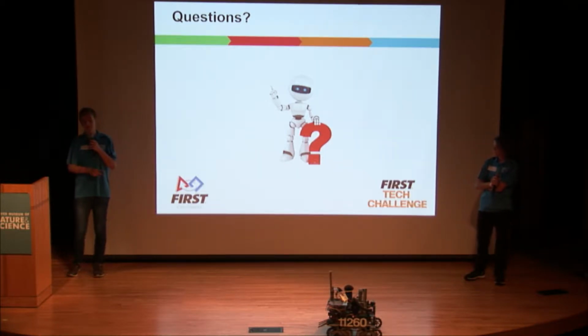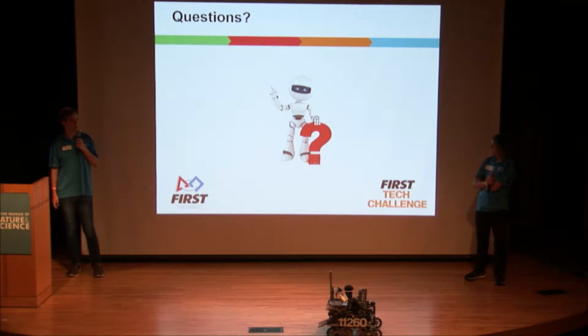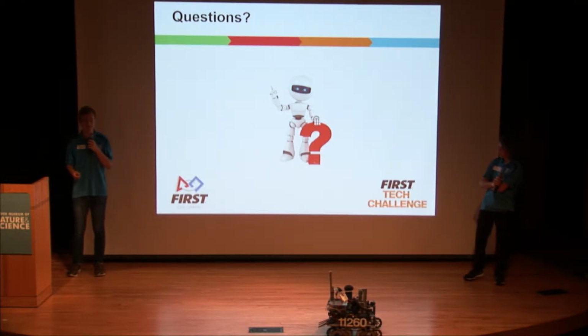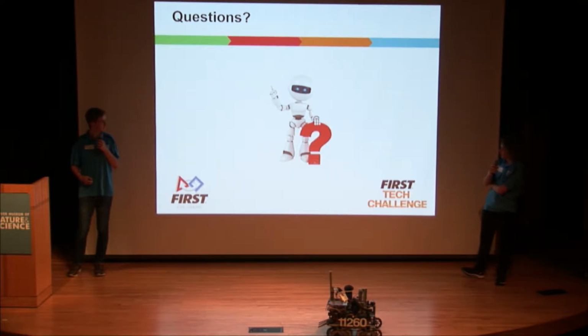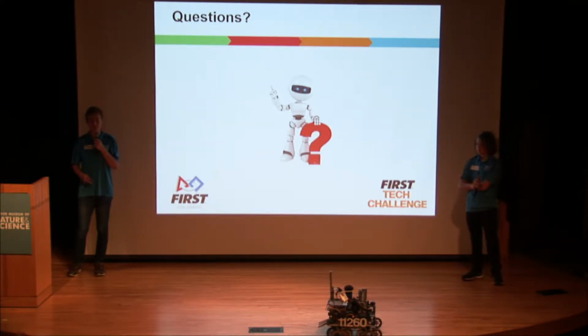Are you talking about the gearbox, the ratio? Last year we ended up going with the 20-to-1 motor because we did want to have better speed, and it did give us enough torque to accomplish what we needed to do. So that is with the AndyMark NeveRest motors. AndyMark NeveRest is the brand of motor.